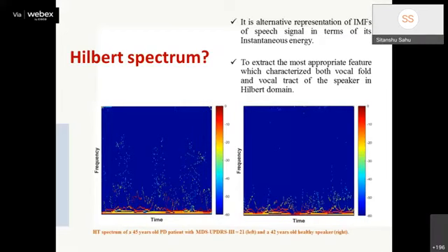So then we find another feature, which is called Hilbert spectrum, the energy distribution in the Hilbert spectrum. This is basically a time frequency representation scheme. Here we try to see the pattern of the Parkinson's disease speech energy distribution and the healthy one. You'll see the energy is getting deteriorated in the frequency domain, and if we can capture this variation in the Hilbert spectral domain, we can devise a new feature that will be more discriminative, meaning dividing the class of Parkinson speech and the normal speech.